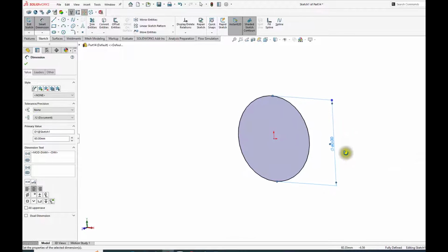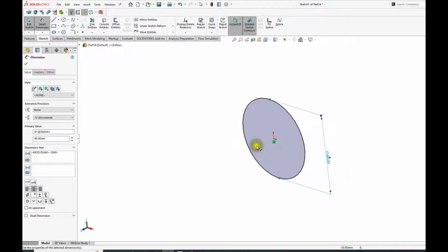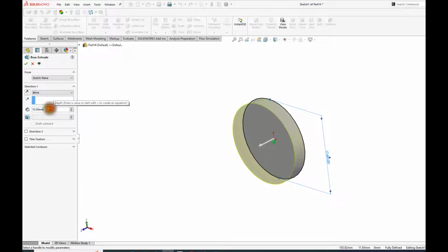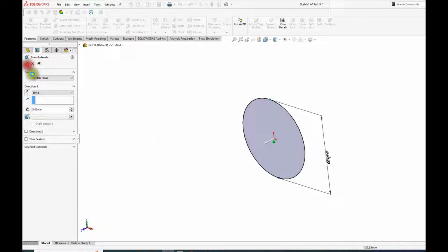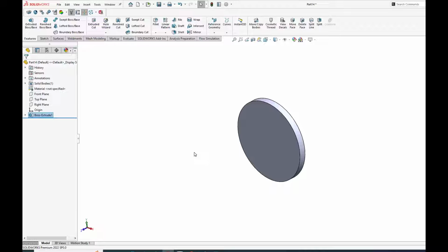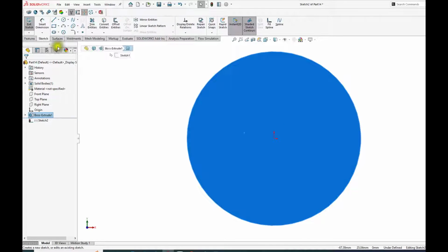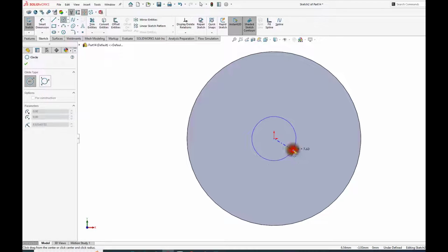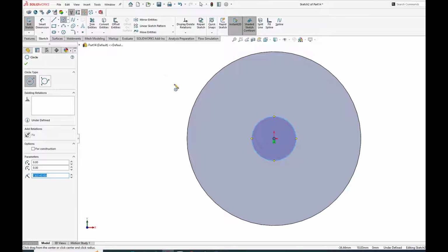And now in that direction, on the Z direction, let's do the extrusion. So we go to features, extrude, and we're gonna do that extrusion. It's gonna be 5 millimeters. That will do. We accept that, and we have the base for our turbine. And the next will be on this face, let's do a sketch again, and that will be for the center that's going to be holding the blades. Let's do that about 20 millimeters.